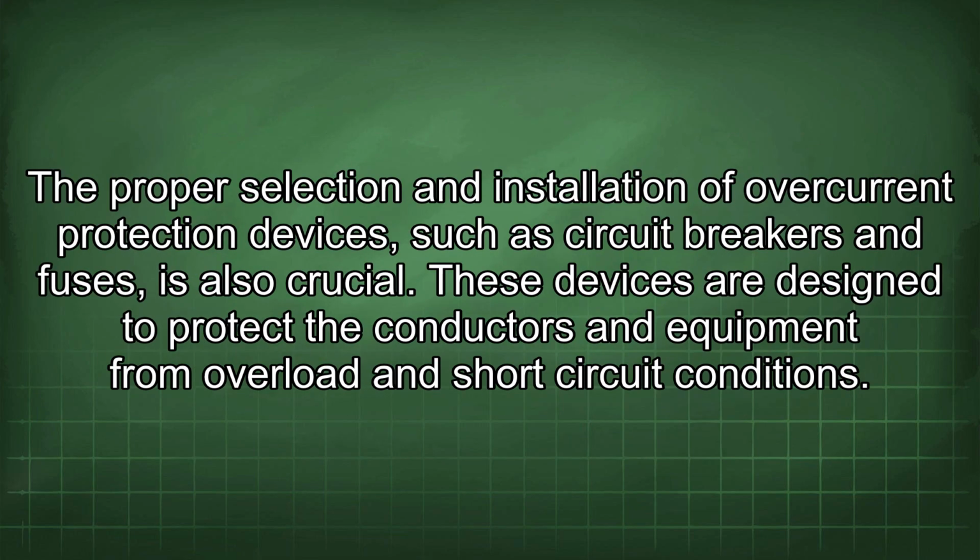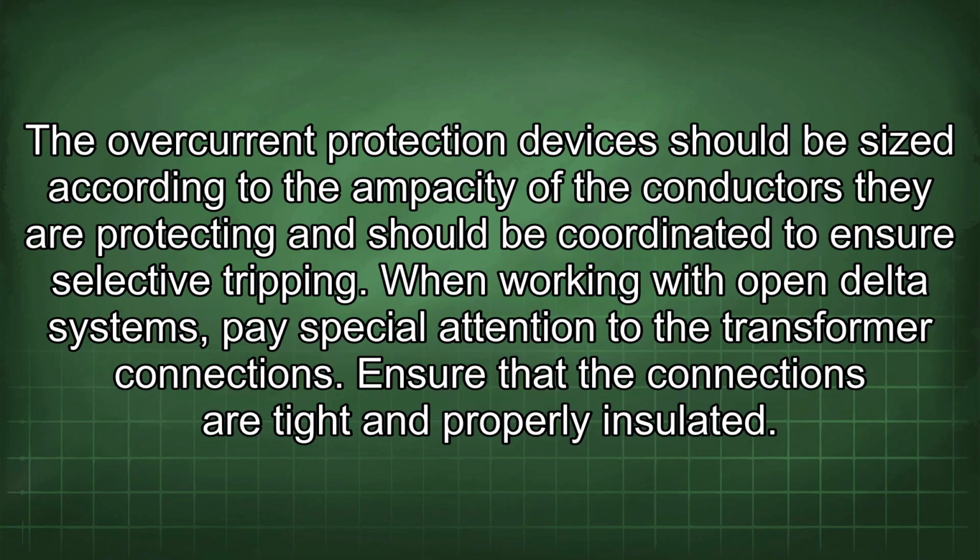The proper selection and installation of overcurrent protection devices, such as circuit breakers and fuses, is also crucial. These devices are designed to protect the conductors and equipment from overload and short-circuit conditions. The overcurrent protection devices should be sized according to the ampacity of the conductors they are protecting and should be coordinated to ensure selective tripping.